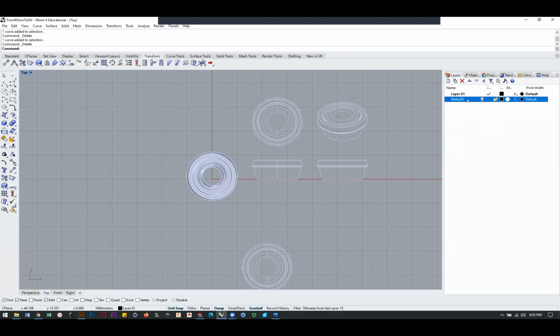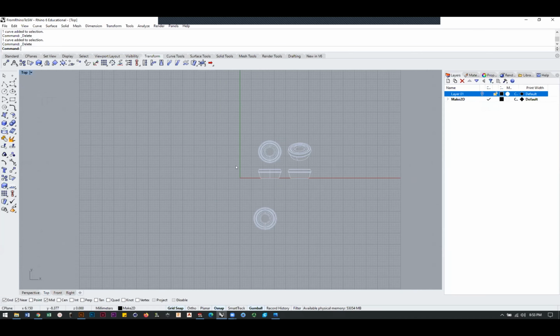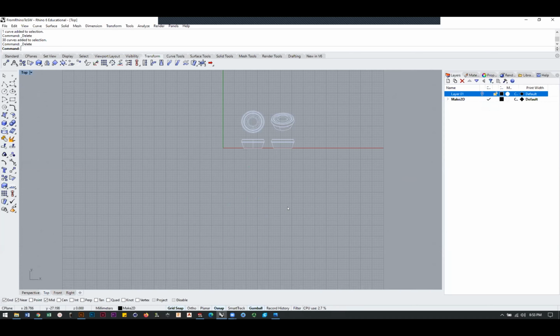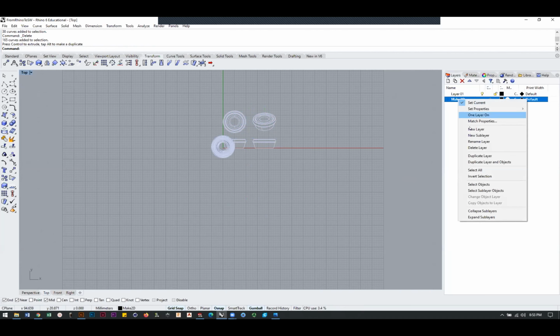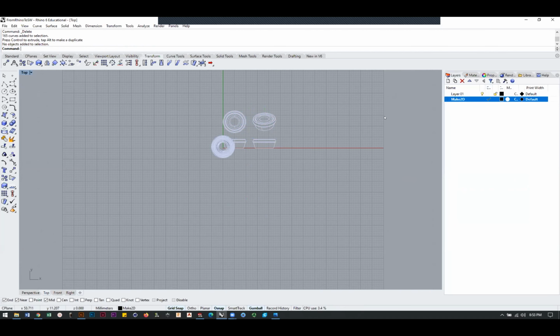You can double click on this layer set to make it your primary layer, and you can hide your main model. Then you can use this line work for presentation purposes. Another point to make too, as we get through this.